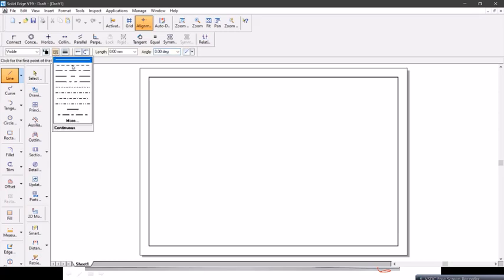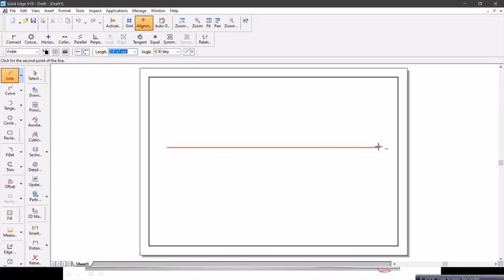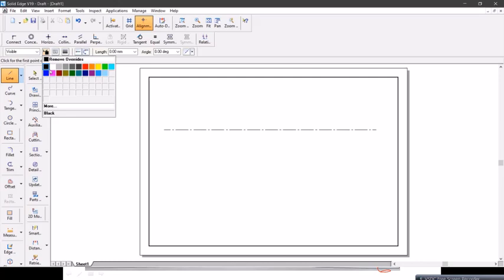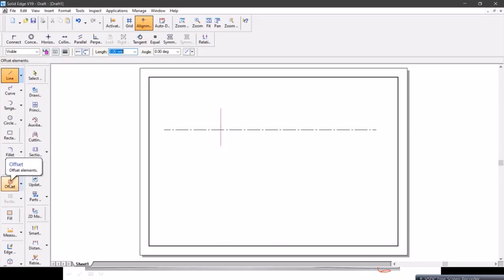Now first you draw one center line here, very thin. Now I will draw two vertical lines here. One vertical line. Now what is the length of bolt? It is 100 mm. I have selected offset, distance as 100, place here.